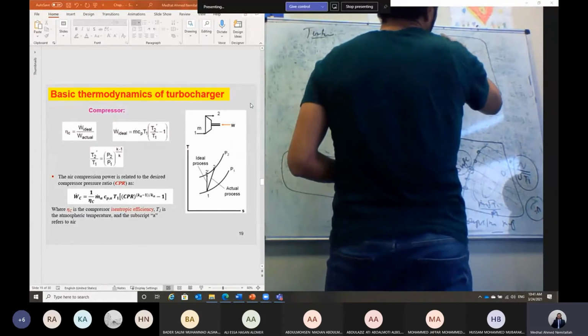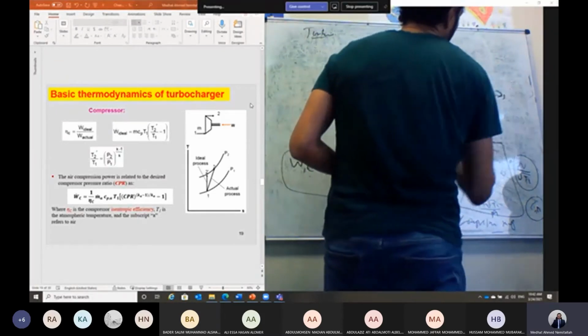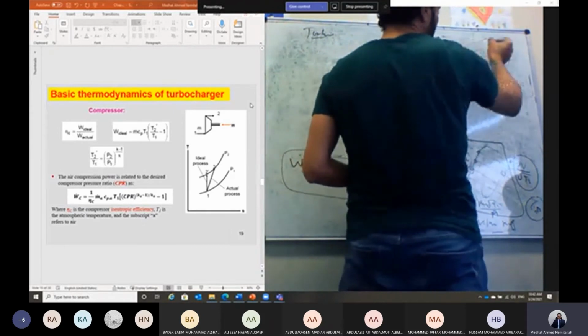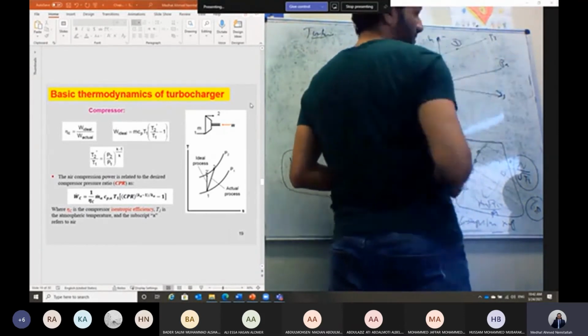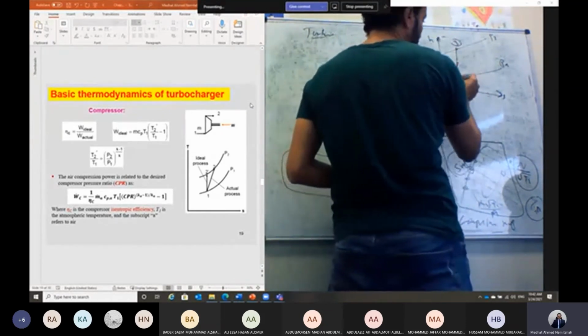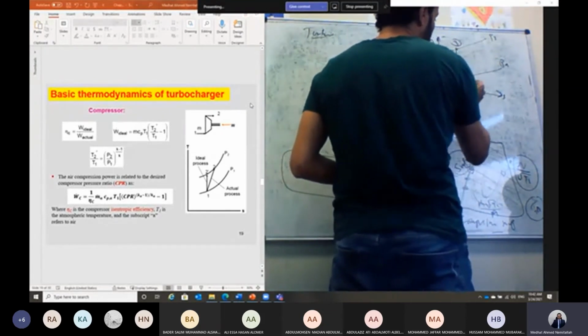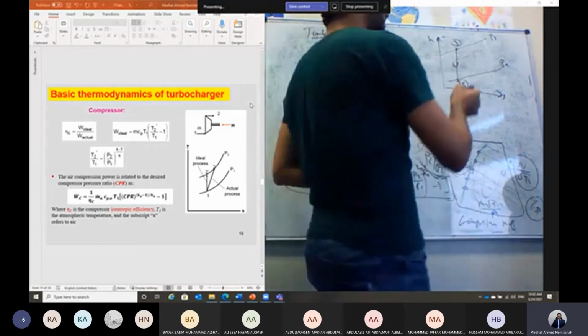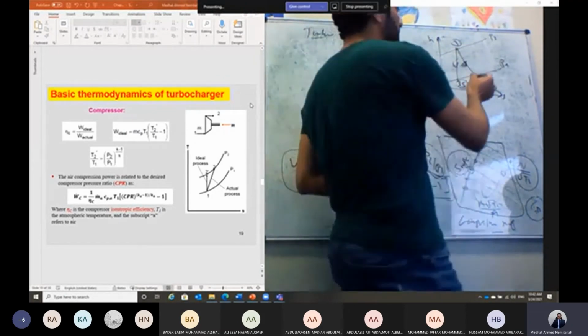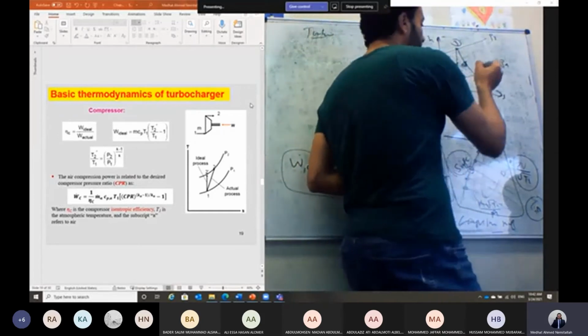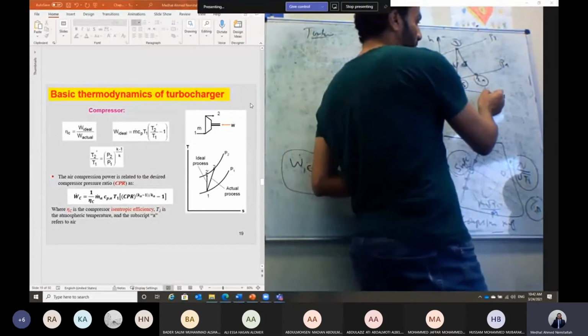So in case of the turbine, if you look at the HS diagram, the process through the turbine is expansion from the pressure P3 down to pressure P4. So let's say this is point 3. If this expansion is isentropic, it will be leaving at point 3S, S which means isentropic, but usually we should have some heat lost. So in this case, the process will actually result in an increase of the entropy.